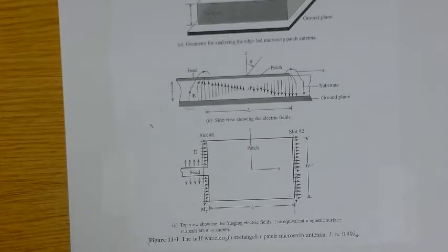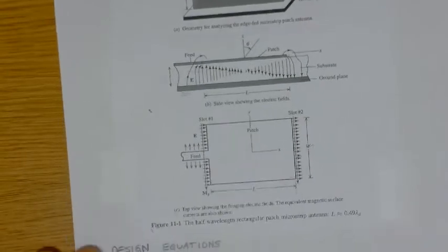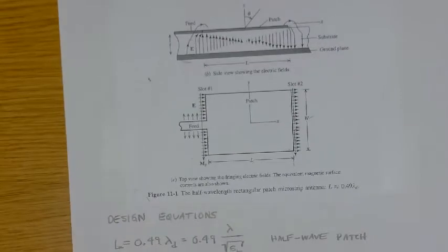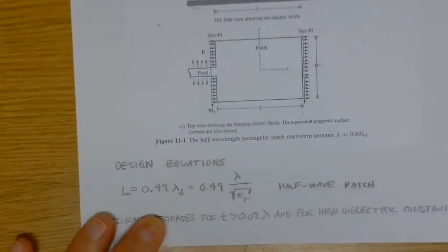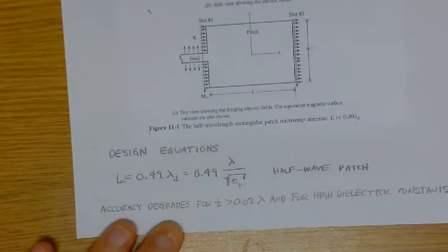And then as you move up higher in frequency and lower in frequency, the standing wave ratio degrades, and the bandwidth is defined as that range of frequencies over which the SWR does not exceed 2-to-1. Okay, so that's a typical definition. Other definitions are used, right, depending on circumstances.